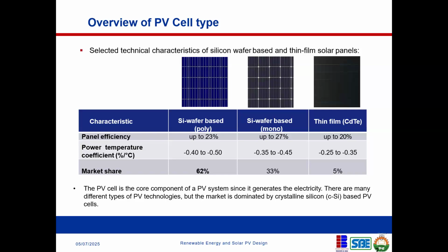Of course, now the cost competitiveness between the monocrystalline and the polycrystalline is becoming more competitive, and the monocrystalline is dominating the market. Before now, the polycrystalline dominated the market, and the reason is because if you look at the efficiency gain of buying a monocrystalline against the cost difference, you find out that the efficiency gain is not worth the extra cost. So in that case, you just go for the polycrystalline.